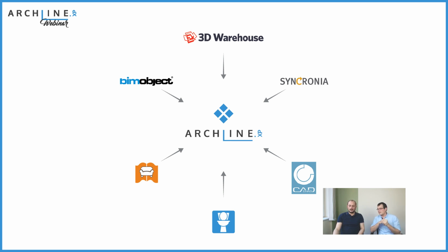Next one is a sanitary library, where do you know anything about this? Well, this is also for manufacturers. This is not built into the software. You need to download a free plugin. But once you download that plugin, you can extend your libraries with other manufacturers' database, and again, from that point on, it works the same. You just search for an item, and you can just bring it in and use it as another 3D item.